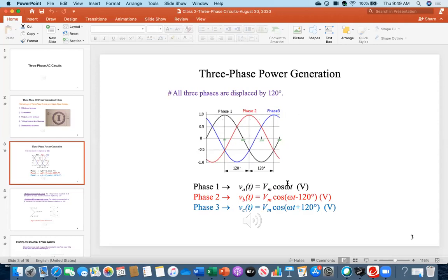So accordingly, those three phase voltages are expressed as VA, and you all know these are time dependent functions, time dependent variables. So Va(t) is Vm cosine of omega t, then Vb is minus 120, then Vc should be minus 240, but to make it similar, 120, 120, anti-clockwise it is plus 120.